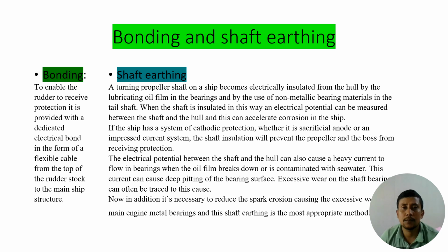And I want to add something else: in ICCP normally we supply 440 volt, and through a transformer and rectifier we get 24 volt DC. And the current capacity of ICCP actually depends on the wetted surface area of the ship, size of the propeller and rudder. I have shown you some pictures in my previous slides to help you understand ICCP, and in this picture the current was showing 500 ampere. It can vary from ship to ship, according to the size of the ship.